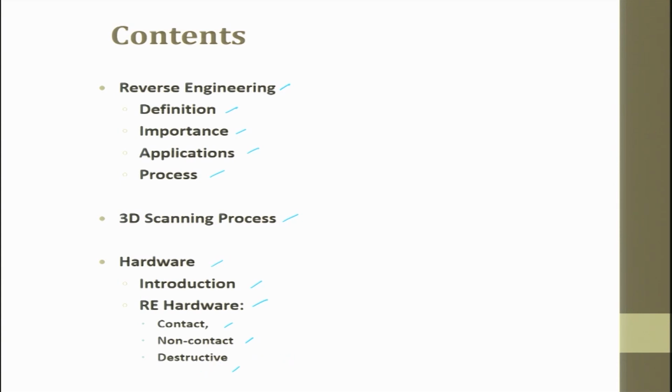Destructive means you are damaging the workpiece or you are damaging the product, and then from the damaged product you are trying to understand what is the mechanism of failure, or understand what is the shape, what is the size, but the component cannot be reused, the product cannot be reused moment you break it. So, contact, non-contact, and destructive. If I touch and then I try to take the measurements whatever I want and make a good use of it, those things are called as non-destructive methods.